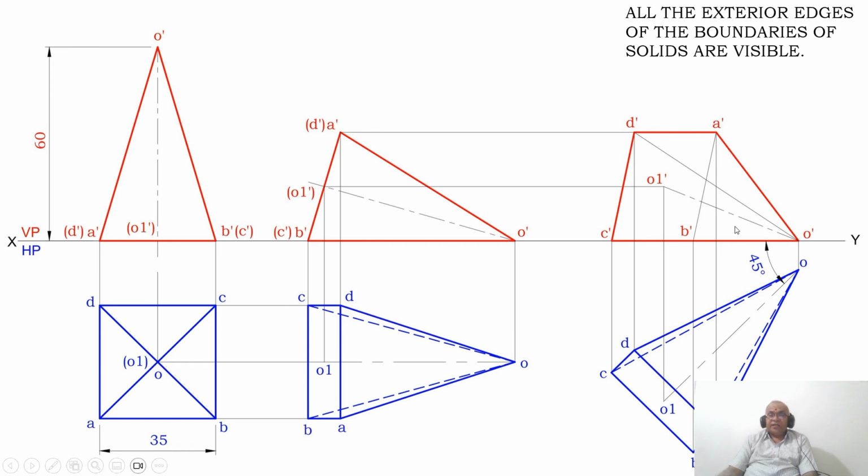You have to get the apparent line. Since the second position top view has the apparent line, and the inclination given in the third position top view is apparent inclination, therefore rewrite the same sketch on the 45 degree line.